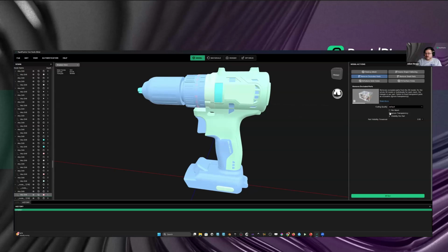You can do ignore transparency. This is usually relevant not necessarily for CAD files, but when you already assigned a material somewhere and it has transparencies, or you import a non-CAD file, like a 3D file from Max, Maya, Blender, which has transparency set up, alpha blending, and so on. Then that is recognized and it can ignore the transparency.